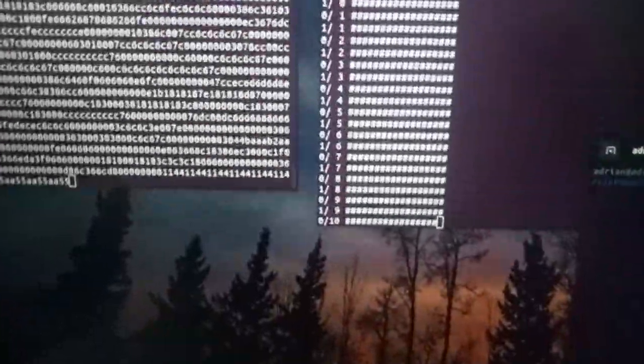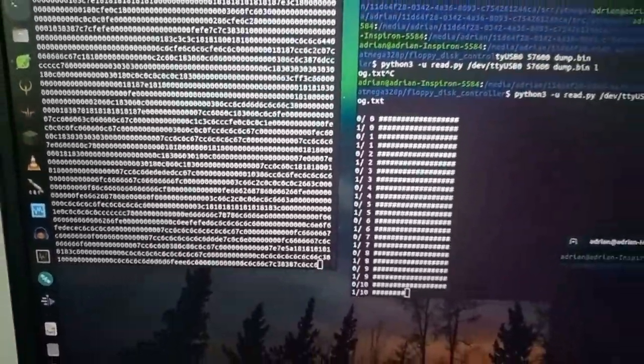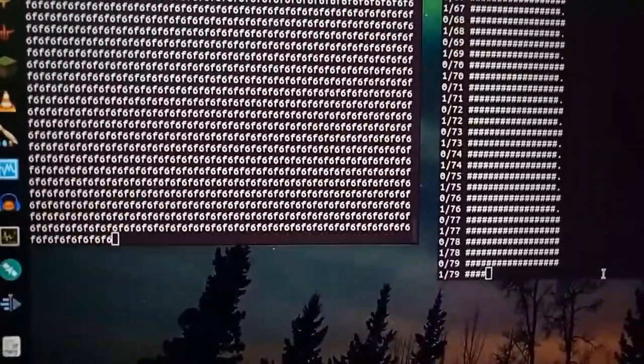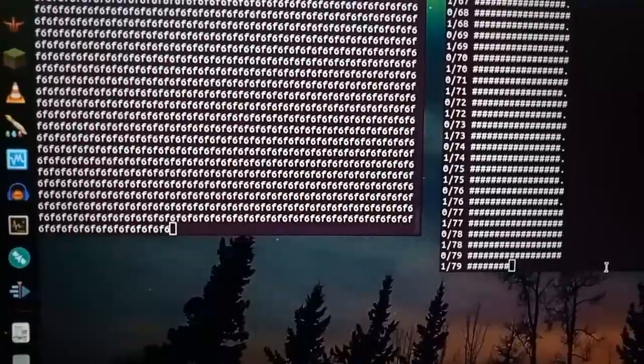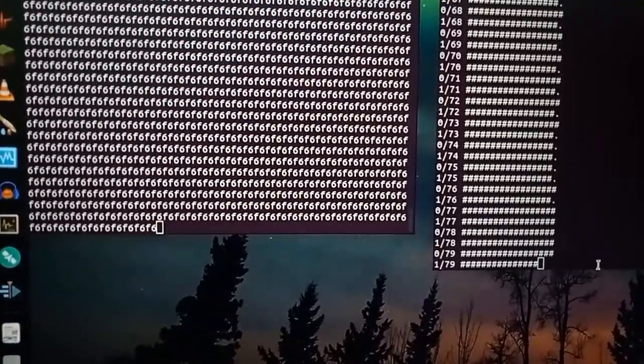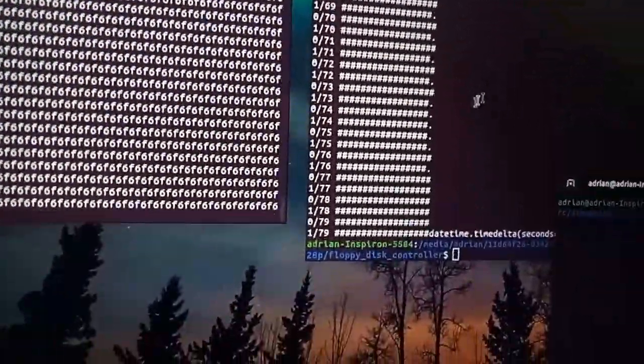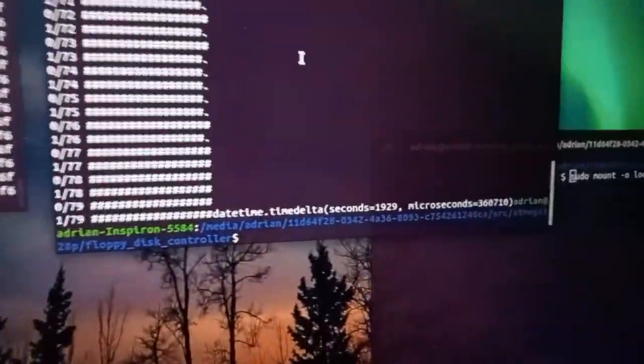All pulse processing is done on the PC in a Python script, which controls the floppy disk using Arduino pinouts, decodes MFM, calculates CRC, and compares it with the CRC read from the floppy disk. If the CRC matches, then that sector can be saved in a bin file, otherwise the controller moves the head back and forward and tries to read the sector again. Slowly, all sectors in logical block addressing order are ripped from the disk to the bin file.